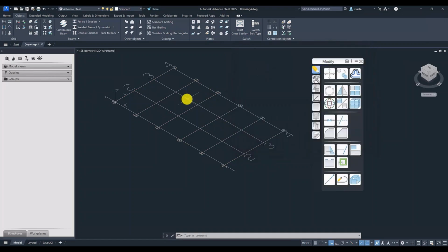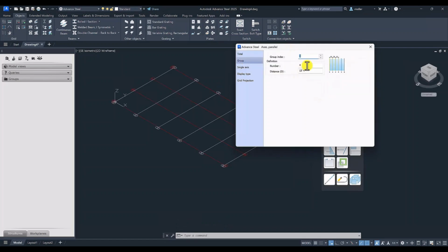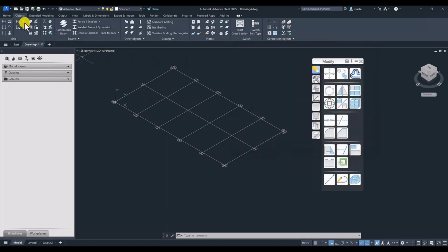Say I were to double click on the horizontal grids, same idea. Maybe I want to turn some edging on this. Now, how this grid looks does not dictate how the drawings look. It just allows me to see things nicer. Maybe just make 3 of them. This is how we start a project with grids. You're going to see up here how I can add more grids, remove grids from where I select. Give it a name, maybe one more extra grid at 4 feet, and I got it in. Everything in here is very grippable, kind of like an AutoCAD feel, where I can just snap that in.